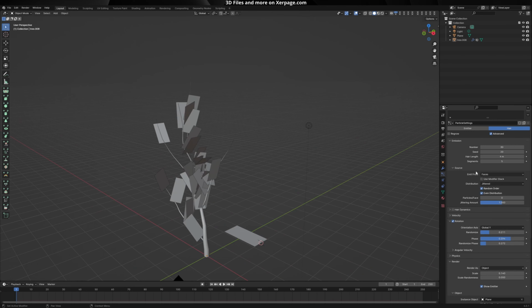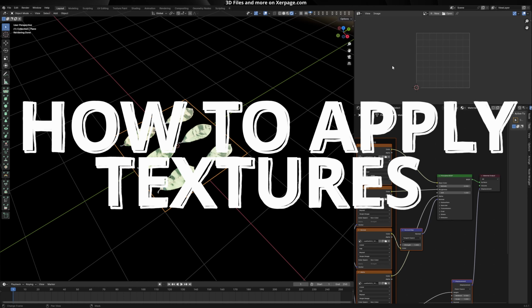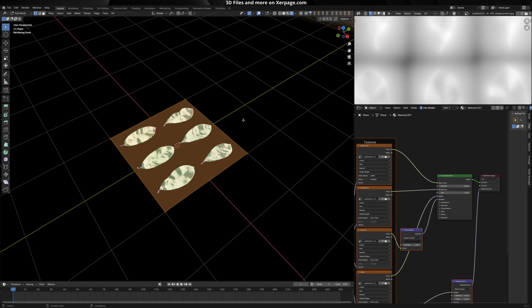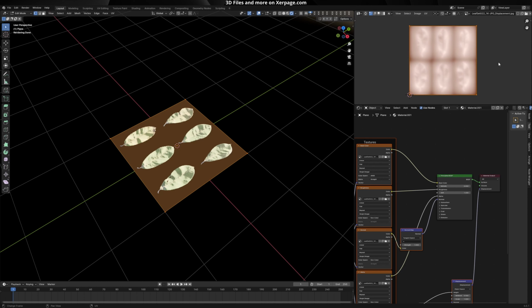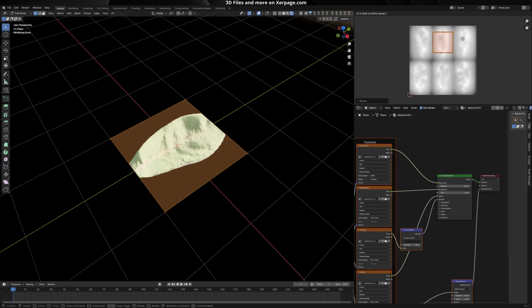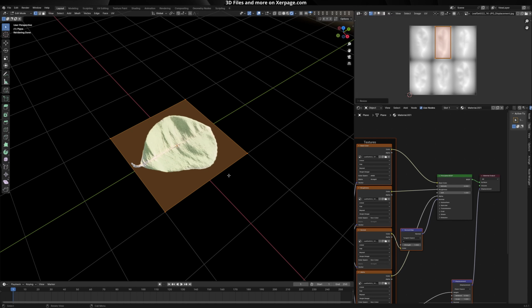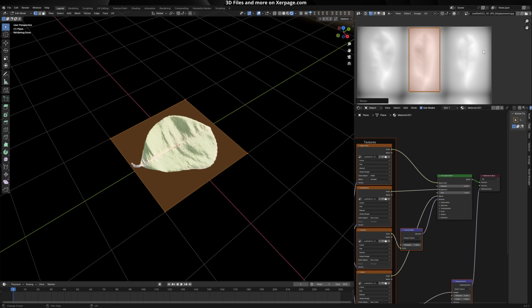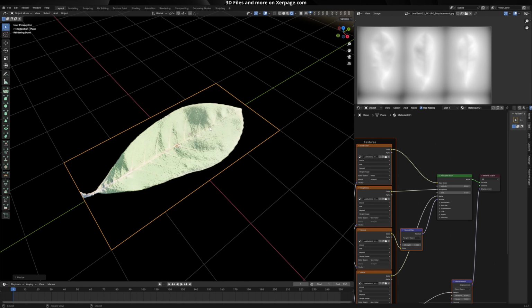You can also go on source and select the vertices. Switch to UV editor tab. Press tab here in order to enter edit mode. Select these vertices and scale it down and select one leaf. Now press something like S, Y, 2 on your keyboard. And do the same thing also in this other tab, S, Y and 2. So now we have one leaf.